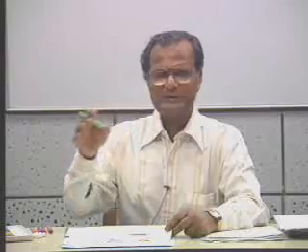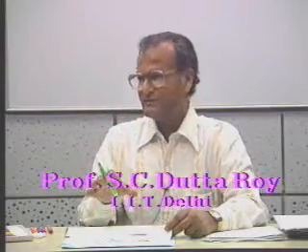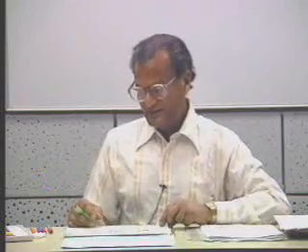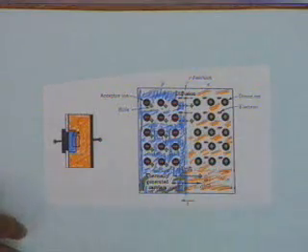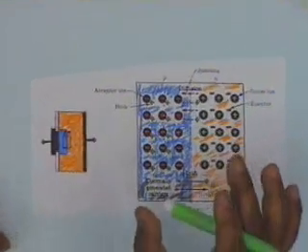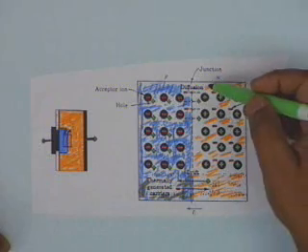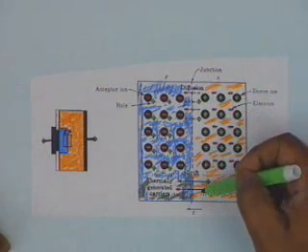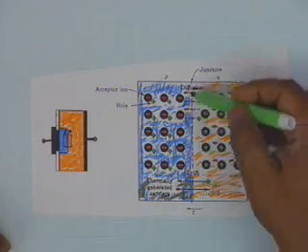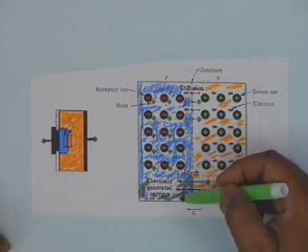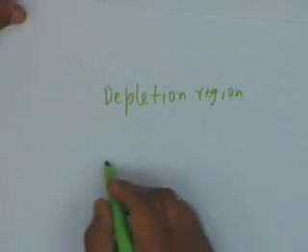If 50% of this class now leaves, then we will say the class is depleted of its strength by 50%. All right. So there is created a depletion region. Now, if a depletion region is created, there are no mobile charge carriers, then the situation is that there are fixed positive charges on the right hand side and there are fixed negative charges on the left hand side, which is precisely what happens in a parallel plate capacitor.